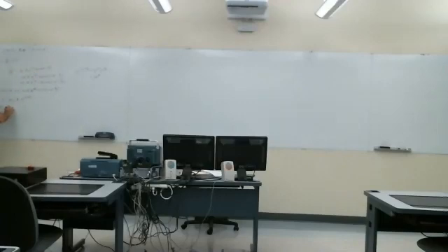So j omega_0 L prime A_I e to the j phi, and gamma A_V. Now I think I have the final result. I can factor out the A_I e to the j phi term out of the right-hand side, and I'll have (R prime plus j omega_0 L prime) A_I e to the j phi equals gamma A_V.